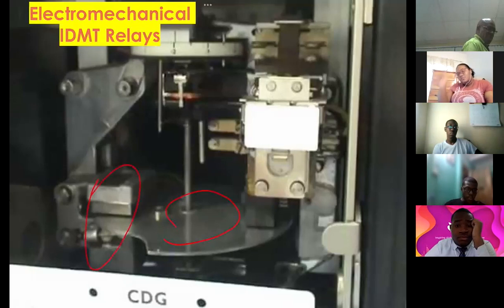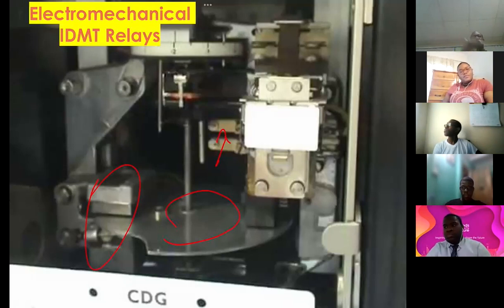These are those braking magnets to prevent overshoot. The contacts are in here. So the higher the current, the faster it moves, which is why there is the inverse relationship. And obviously, the faster it moves, the quicker it will operate.